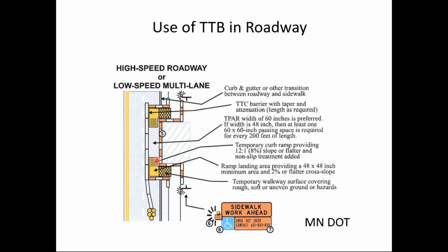And so notice here, the pedestrians are in a zone of safety. They've got the pedestrian channelizers here, shielding them from the construction activity. There's temporary traffic barriers on this side, shielding them from vehicular traffic. So as long as they're in this corridor here, or this path, the temporary path, alternate access route, there's no danger of conflict with vehicles. So we don't need detectable warnings.